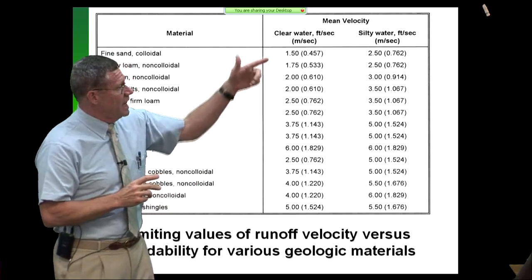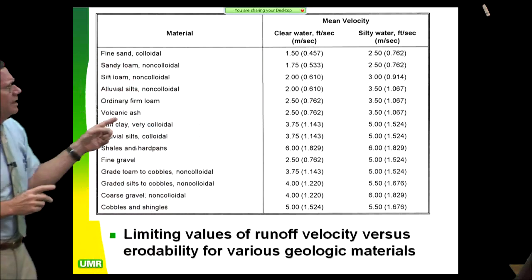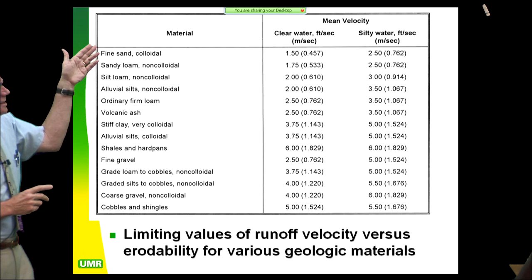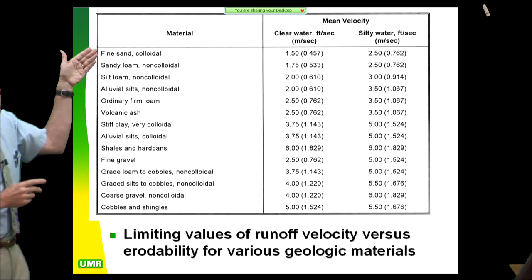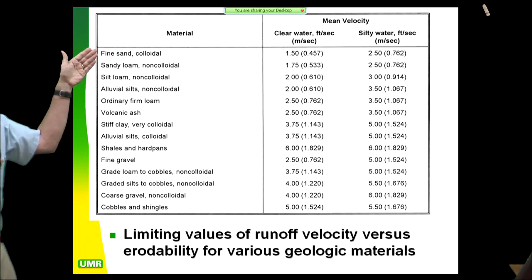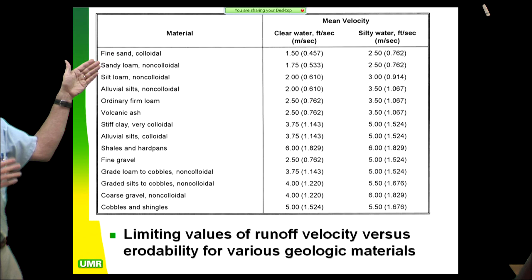And what you have to have here is clay. If you look at these different materials, sand doesn't have a lot of resistance to erosion. It doesn't have any cohesion. It's a frictional material, nice clean beach sand, about a 33-degree phi angle of internal friction, no cohesion. Sandy loam is going to have a higher apparent cohesion and a higher apparent friction, and as long as it doesn't get saturated, it can do quite well.